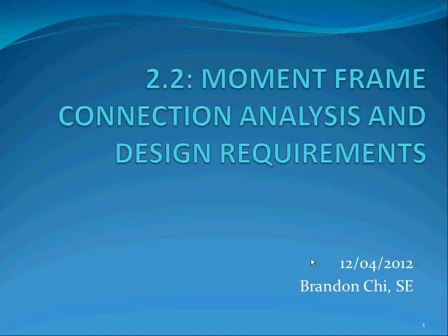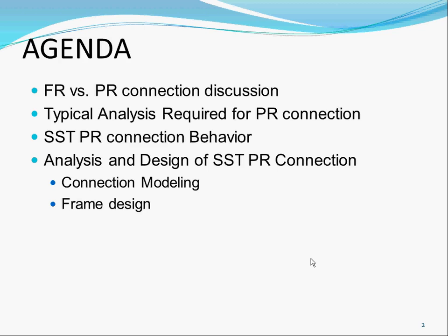Okay, this is section 2.2 on moment frame connection analysis and design. For typical welded connections and bolted connections we saw yesterday, all of them are considered to be FR connections or rigid connections per code. Ours is a little special. It's considered a PR connection, and I'll go into what the two are. Because of the PR connection, there are more analysis and design requirements for our connection.